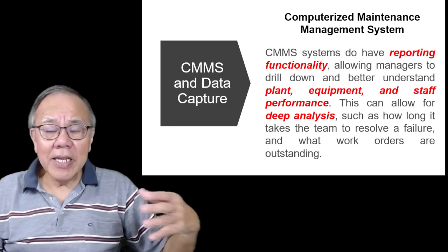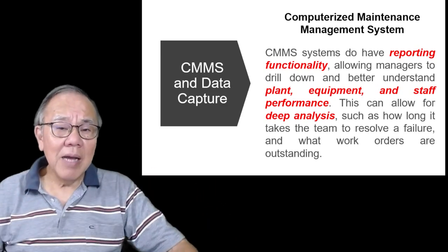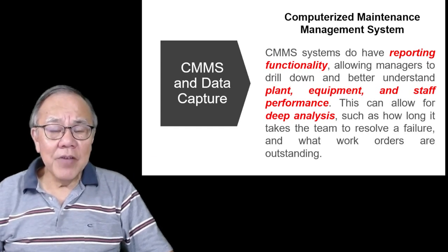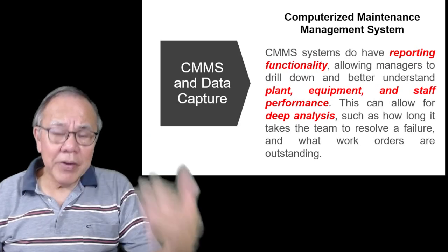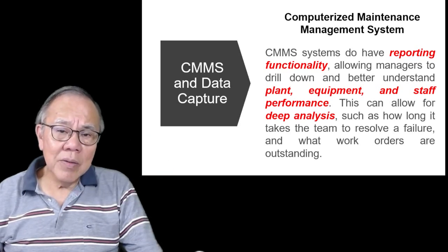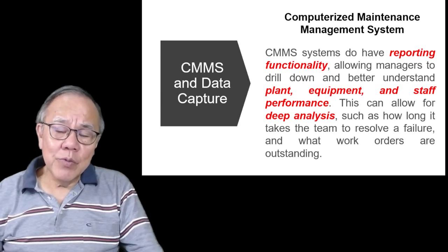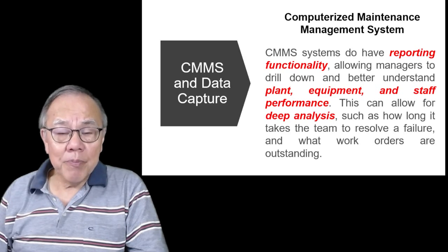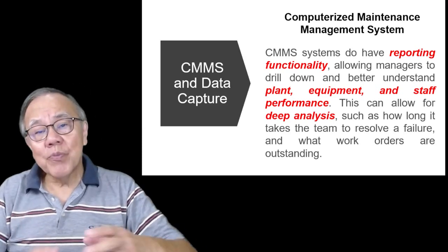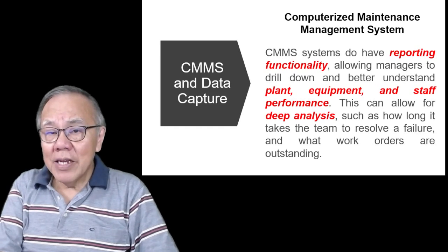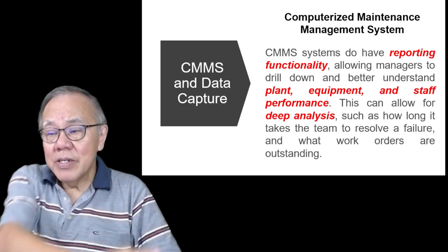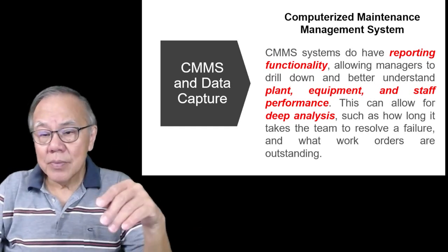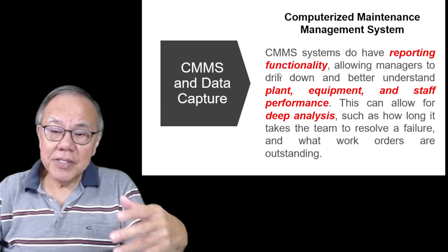and over an extended period, you can then look at this equipment and say, most of the time, what sort of breakdown does it have? And if every time it is a bearing problem, what did we do? We did the same thing and it happened again. Maybe our strategy of repairing is wrong. Therefore, you need to break that out and do a root cause failure analysis. That's where some of the maintenance strategy comes in, so that you can do some analysis and so on.